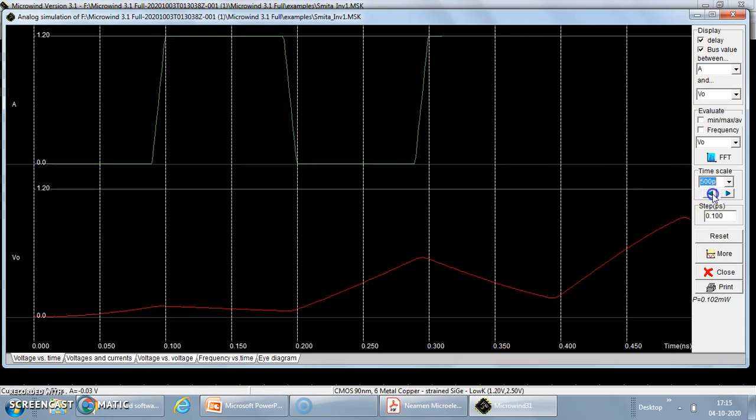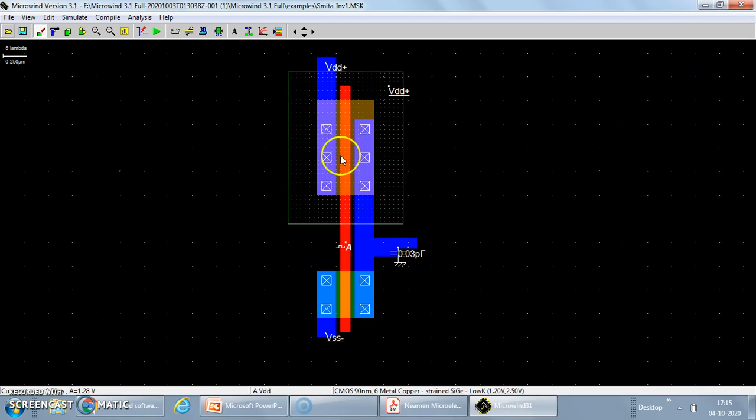So rise time and fall time. As we increase the value of capacitor, it is fast charging and again discharging, but it is not such a sharp change. So if we make the value of the virtual capacitor as a load as low as possible, then it moves towards the exactly square waveform. So by changing the value of capacitor, it allows us to change the rise and fall time of the inverter output.